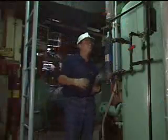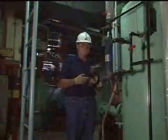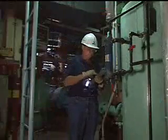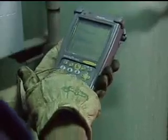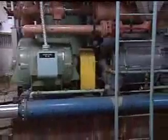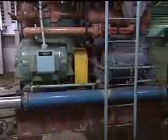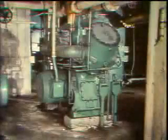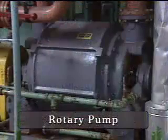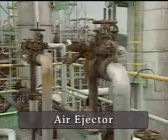Airflow monitors or gauges provide an indication of the amount of air being removed from the condenser shell through the outlet piping. If the airflow is higher than normal, there could be an air leak into the condenser shell. Vacuum pumps are designed to remove air from a system and in doing so create a vacuum. The three most common types of vacuum pumps are reciprocating pumps, rotary pumps, and air ejectors.